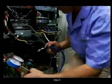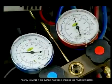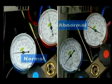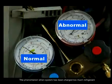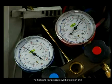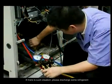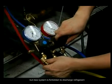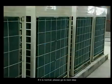Step 2. Measure the system pressure and compare with the normal system nearby to judge if the system has been charged with too much refrigerant. The phenomenon when the system has been charged with too much refrigerant is that the high and low pressure will be too high and the discharge temperature will be too low in the operating system. If there is such a situation, please discharge some refrigerant, but a new system is forbidden to discharge refrigerant. If it is normal, please go to the next step.